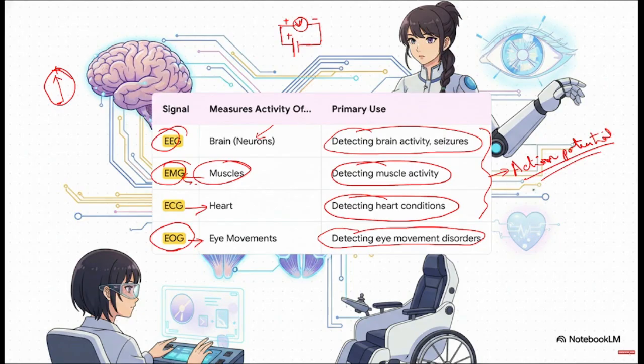So what happens when we move our eyes in the up and down position? We get signal in the orbital electrodes, and if we move our eyes in the left and right direction, we get signal from the canthi electrodes. Please be reminded, any kind of biopotential amplifiers are differential amplifiers.